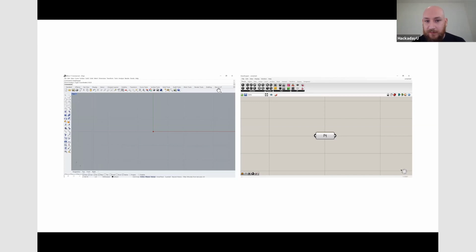So here's an example, and I've done a screen capture of both sides of the screen. We'll start off, create a point and specify that point as 0, 0, 0. And you can see this red X, which represents a Grasshopper point. Everything that we draw in Grasshopper will appear as red in Rhino, green when selected. And then I would add a circle component. Each of these components has inputs on the left and outputs on the right.